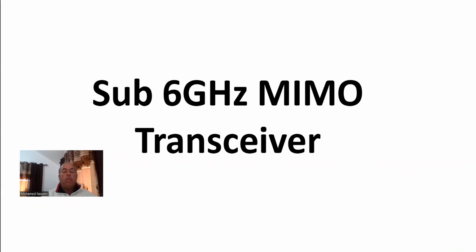I suggested this from the beginning. We know that there's a difference in bandwidth between the sub-6 gig and the millimeter wave bands for the 5G small cell transceivers. But last time I designed a sub-6 gigahertz small cell 1 watt transceiver that has a broad bandwidth, where you could scale the filters down, so you could actually use 400 megahertz bandwidth. The low power section of it will become an intermediate frequency to the millimeter wave transceiver. From a sub-6 G transceiver, which operates from 2 to 6 gig, you would need only an up converter and down converter to take it up to the 28 or 24 to 50 gigahertz, somewhere in there. That's the approach I have.